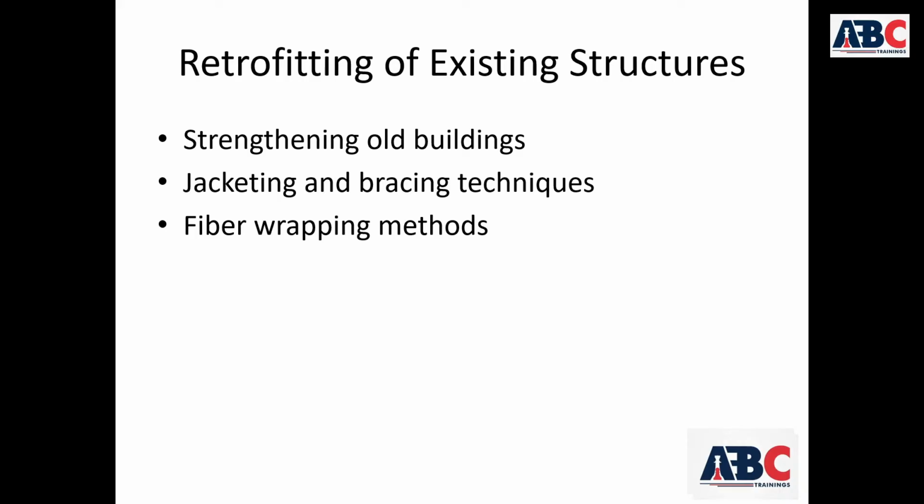Many buildings that exist today were constructed before modern seismic codes were implemented. Why is retrofitting necessary? Retrofitting becomes necessary when buildings do not follow seismic codes, when structural cracks are observed, when there is a change in use, or when there is increased load.